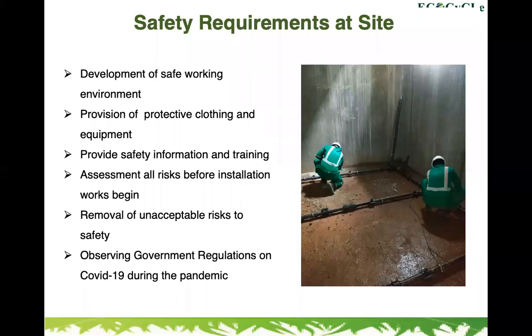What that means is, if you have people already living in the house, either the sewage has to stop flowing in there, by diverting it elsewhere, or the occupants move away, maybe for a week, so that what you have as existing is emptied, cleaned, and made safe for us as a team to go in. So that's how we work it out if it's a conversion.